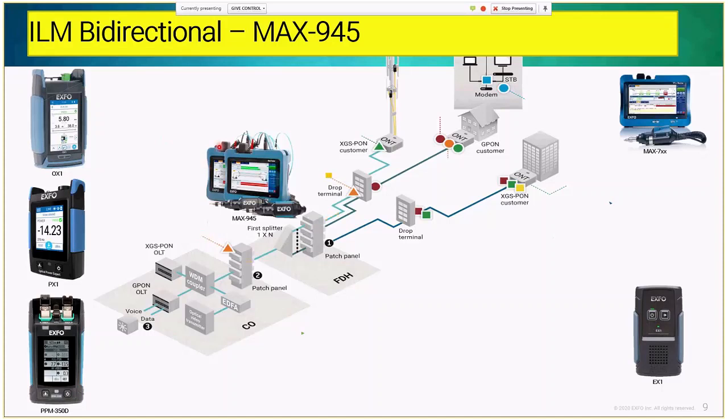As part of the standard, what is recommended is to always have bidirectional measurement, where you can inject, for example, the light here on point A, and then the light will go to point B, and the measurement from these two points will give you the loss, the attenuation on your signal, and what your path is. This is the equipment that can go through the splitter. It can be used from the customer house to the CO.